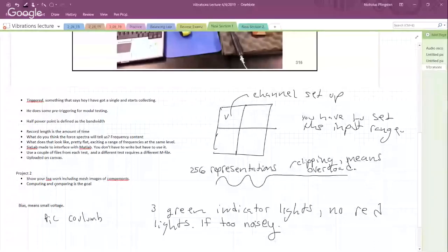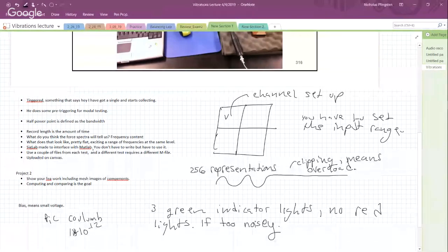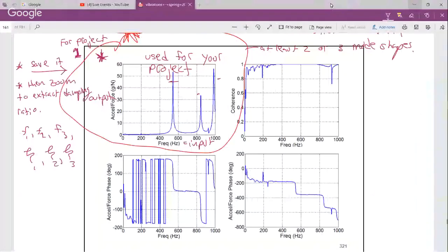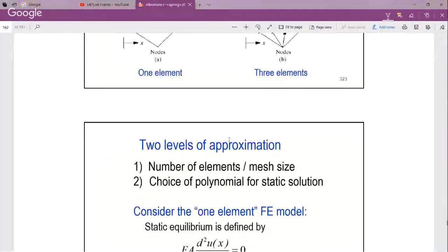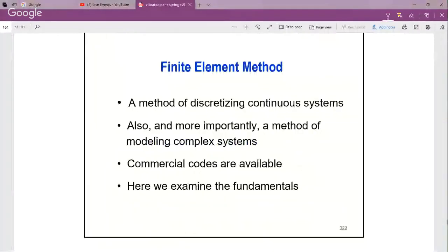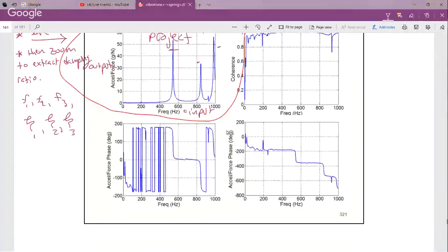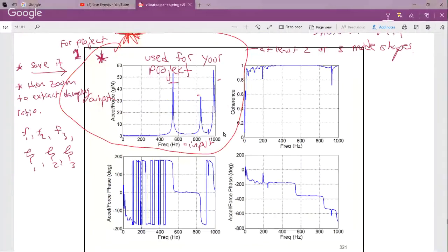So the bias input setting provides the power to do that. The other two input settings are AC and DC. The AC setting filters out any DC offset. So if you're measuring something that you know has no DC component, or it does have a DC component but you're interested in the fluctuations, the part that varies, which you call the AC part, then you use an AC setting. What that does is filter out the DC.